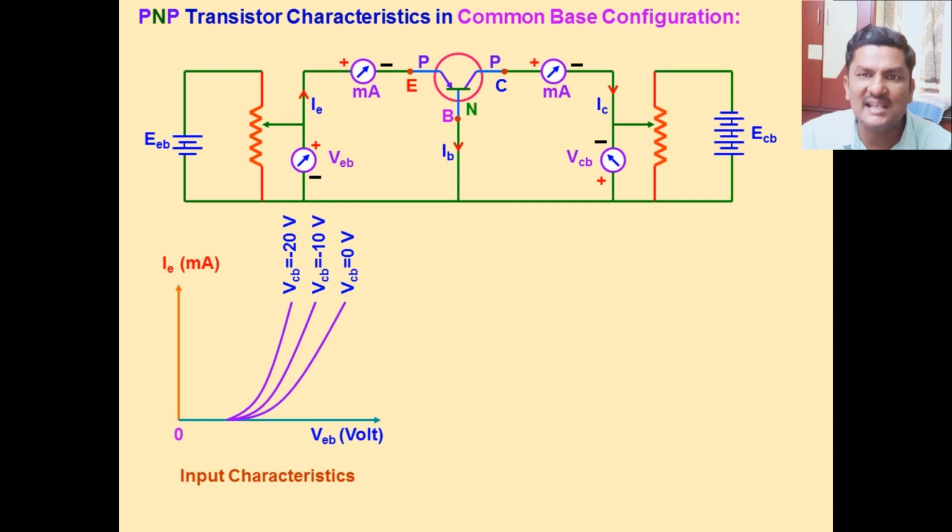If we consider silicon, and the applied voltage is less than 0.7 volt, charge carriers cannot cross the depletion layer, so there is no current. When the applied voltage is equal to or just above 0.7 volt in the case of silicon, there is a chance of charge carriers moving from one side to another.